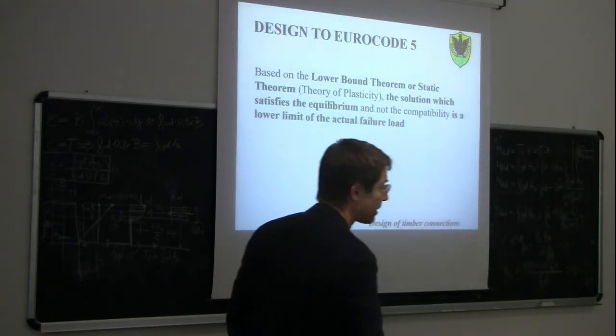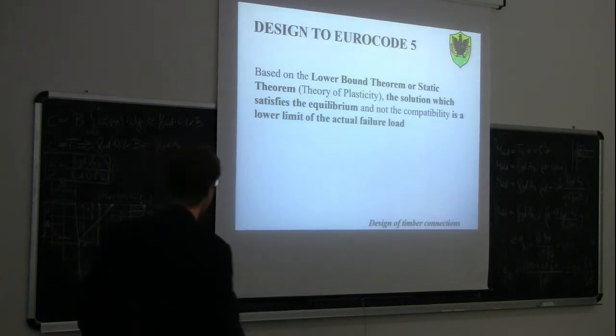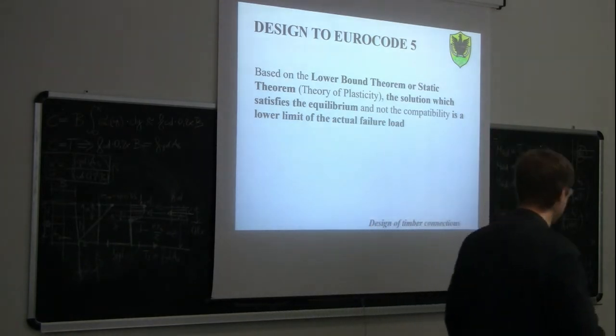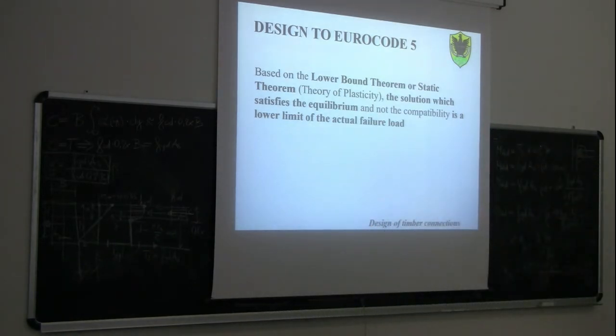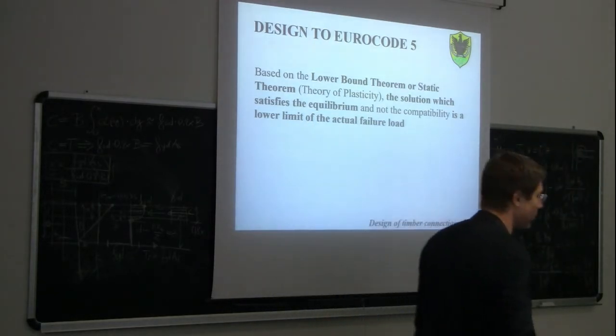As I said last time, there is a theory called lower bound theorem or static theorem, which basically states that if we have material with this property, with infinite ductility, and if we are able to find a solution which satisfies equilibrium and not necessarily compatibility, this solution will be a lower limit of the actual failure load.